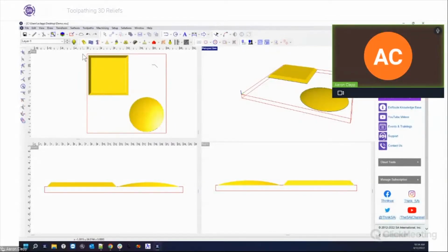So if you're going to make any other modifications to the relief, you need to do that before you do a path and before you move it into the plate. Because once you move it down into the plate, sometimes if you add reliefs or subtract reliefs, you can get some wonky things that happen just because it's expecting you to be starting from the top of the plate, because that's where its reference point is. So that's going to be really important.